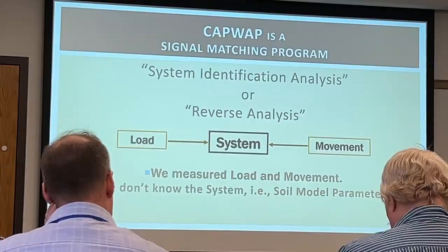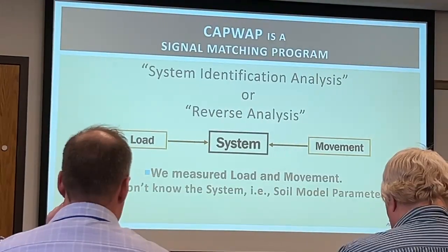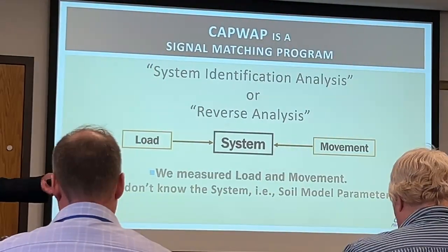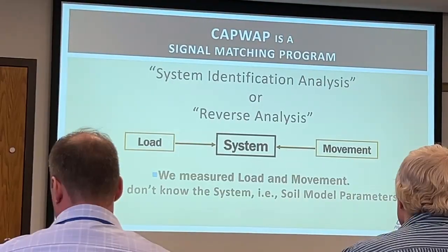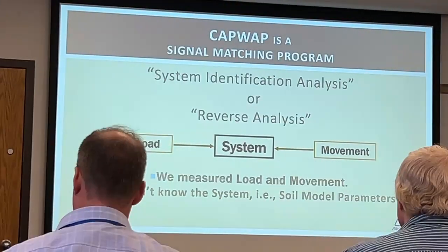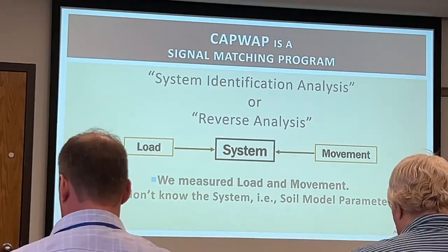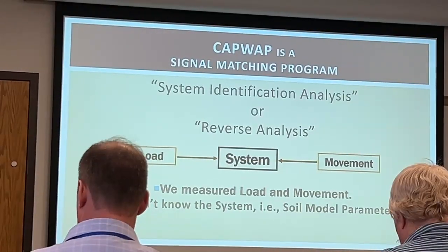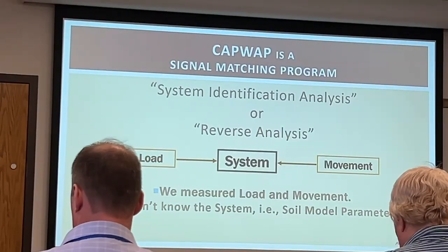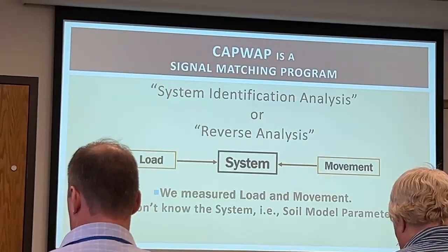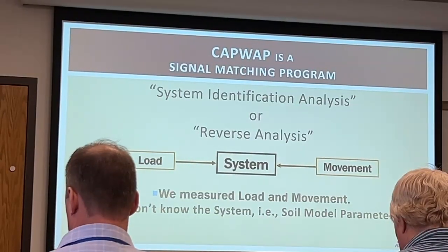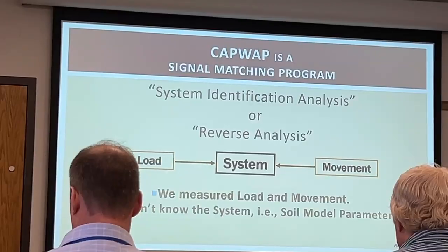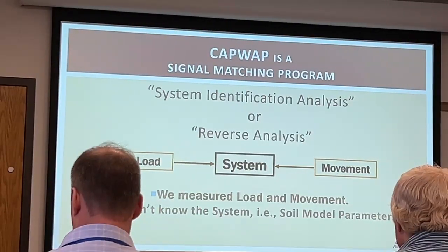We said the resistance distribution along the shaft and at the toe comes from a calculation based on what we saw in the field from in situ testing, or just the soil type. Here, we're saying we're going to model those independently and match it based on what we observed instead of relying on the geotechnical analysis. The geotechnical analysis gives us a place to start, but we need to be willing to shift that around a little bit to match what we've measured in our construction site.